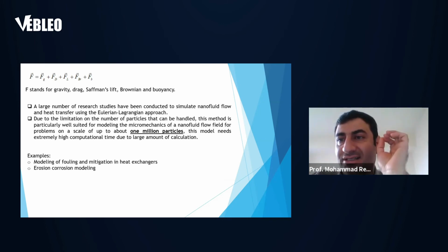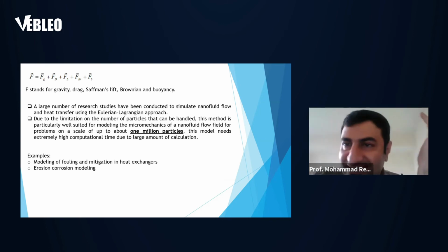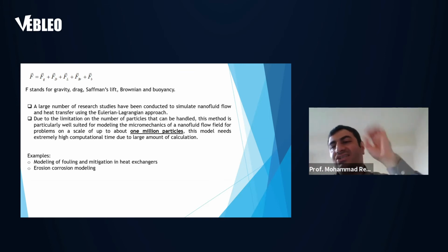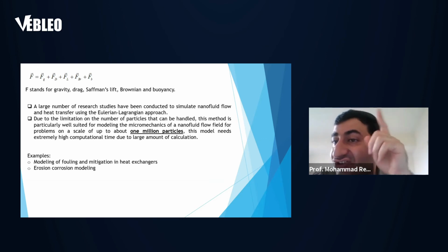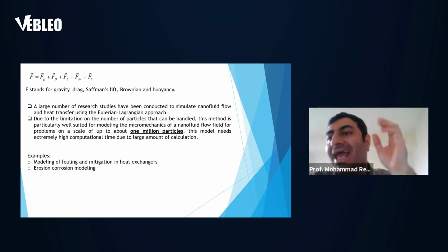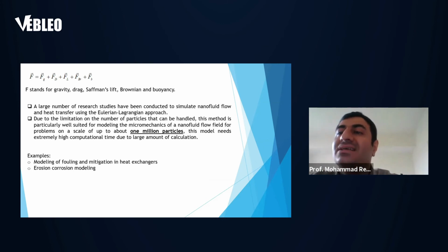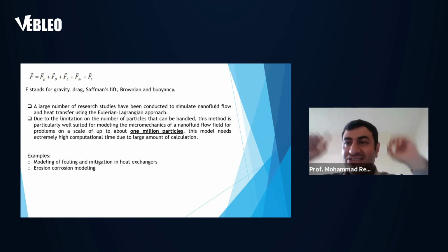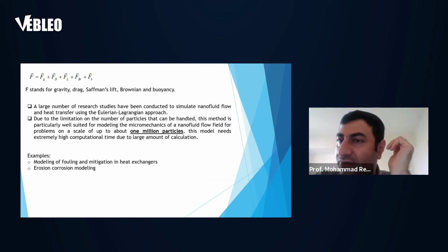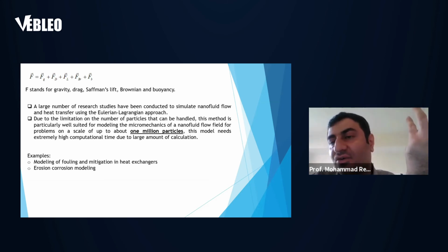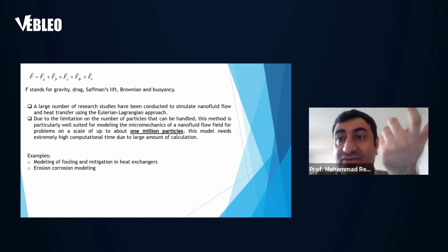The first limitation, which is actually about the existing computer, is that we inject particles inside the fluid and we track each particle. It's not just that you inject the particle, that is your point of view, but you want to track each of these particles. With present computers, you can inject a maximum of about 1 million particles inside your fluid. If you have more particles, this model will not work for you. It's just a limitation of the software and the model.